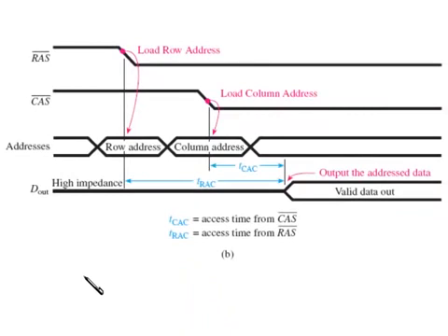So there is some precise degree of timing that takes place. On the address bus, what we'll do is set up the row addresses on A0 through A6, and then we'll drop the RAS line low. This high to low signals the DRAM chip that it has valid rows. That goes into a row decoder, and then we take the address bus and change it to the columns. At this point, we have valid column information. We drop the CAS line low. Now the column addresses go into the column decoder.